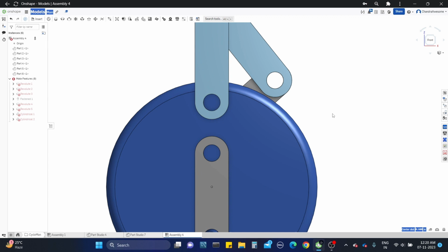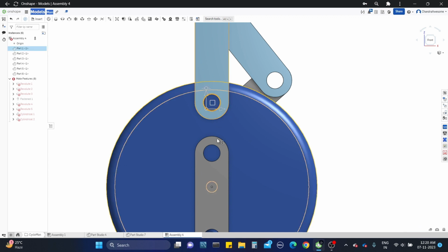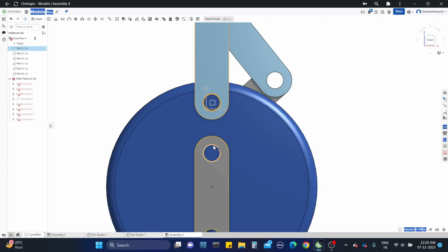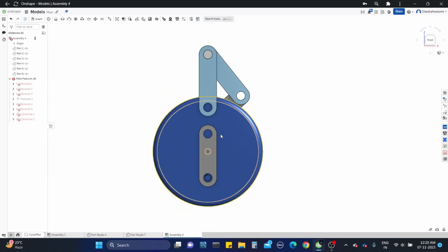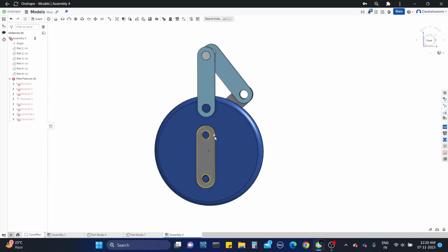How much should it be center to center? To rectify it, set the center support plane, and here it will show 0.608. So we need to increase one of the blocks, otherwise the error will be 0.608. Switch back to Part Studio.